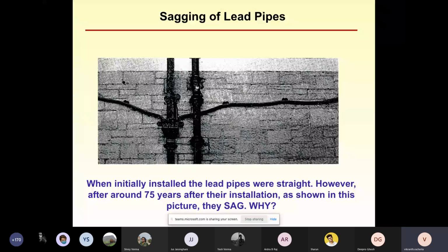Why do you want the gap between the blades and the outer cover to be small? So that as much air passes through the turbines as possible. You want the air to pass through the blades. If it just passes from the top, then basically you achieve nothing. Your efficiency drops considerably, so you have to maintain a very small gap. Now, in this scenario, when the blades are rotating, what is stressing the blade? What is causing internal stress?